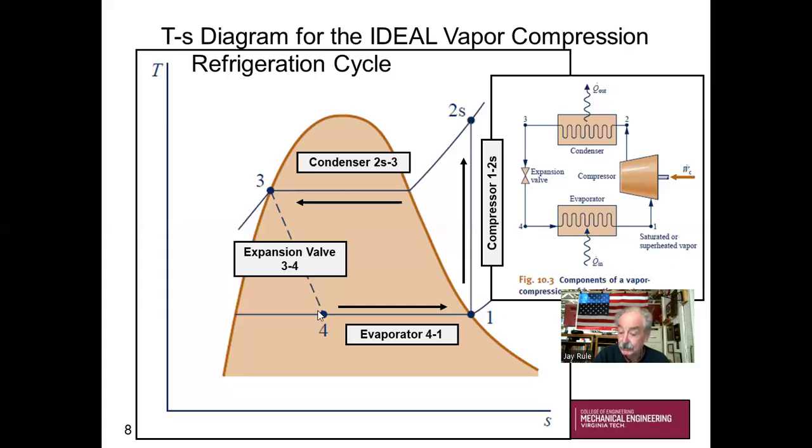Expansion valve. Well, it's very irreversible. So even in the ideal cycle, we have some built-in cycle irreversibilities that we can't do anything about. And then finally, the evaporator, constant pressure evaporation. So spend some time. I'm vamping a little bit to give you some time to eyeball the 4 components and try to see how the 4 components are associated with the ideal TS diagram, temperature entropy diagram, that we're going to be using throughout Chapter 10. Hope that helps.